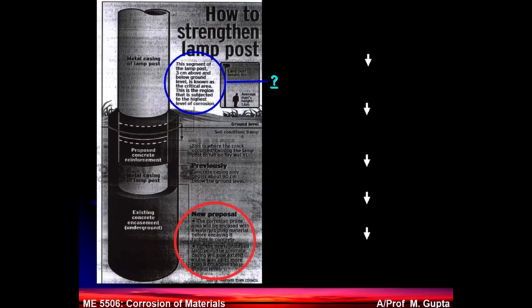Because steel is all hidden inside the zinc layer, even if you lose some of the zinc layer over the years, some cracks may come or it can completely dissolve off, it will still keep protecting iron. Remember the concept that zinc has a much more negative electrode potential when compared to iron. So it always becomes an anode. So as long as it is there, it will still save.